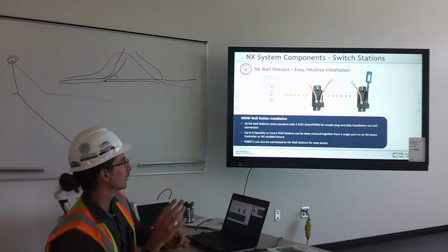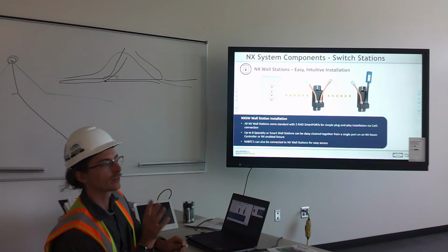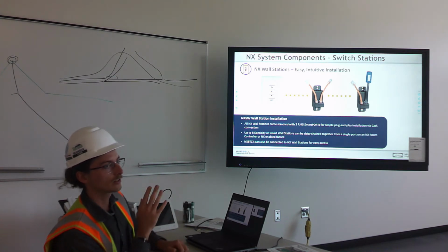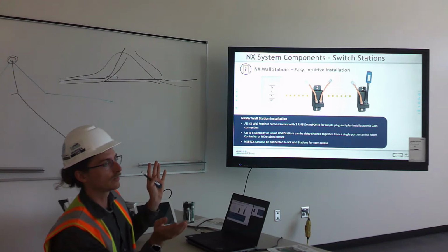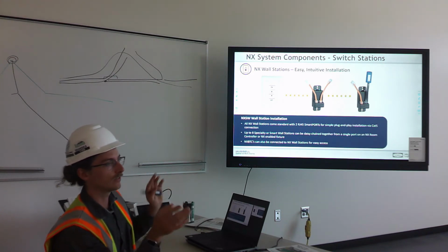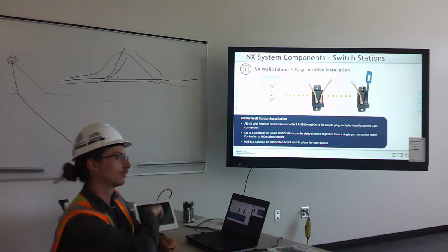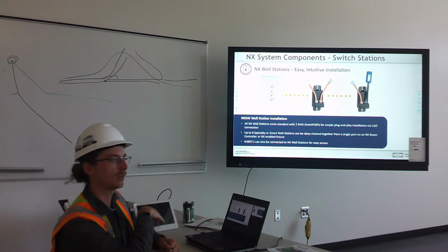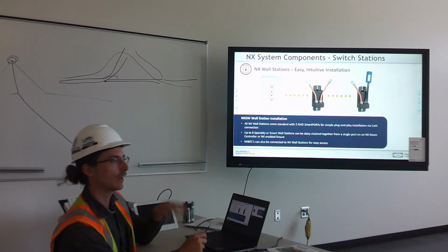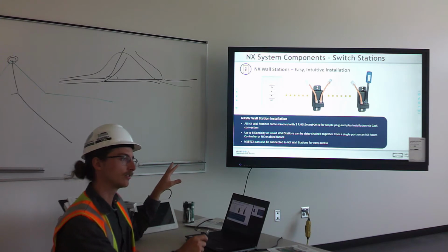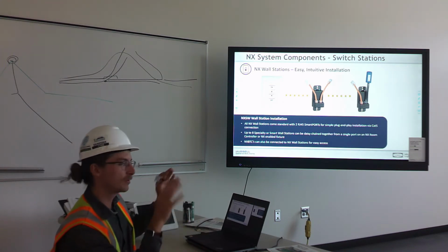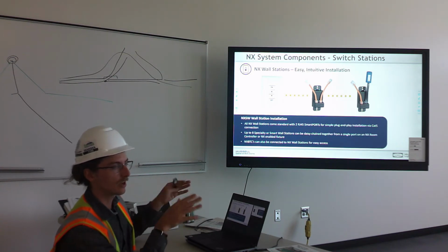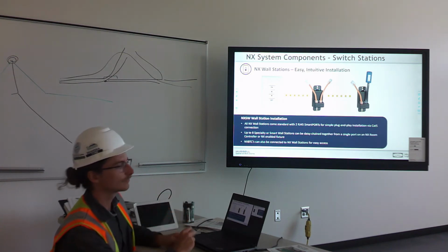But just to fill in what you were talking about with the program, they're set up to turn on at 6 a.m. and then the sensors are disabled until 8 p.m. So they won't shut off even if there's no motion in the hallways. So they're locked on 6 a.m. to 8 p.m. Monday through Friday, and then at 8 p.m. they start listening to the sensors. So if there's still people moving around, they'll stay on. If they're timed out, then they'll shut off.